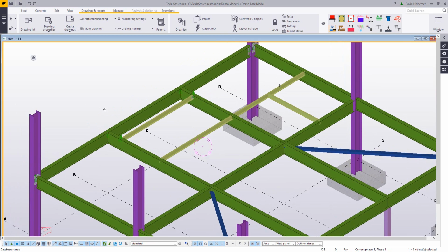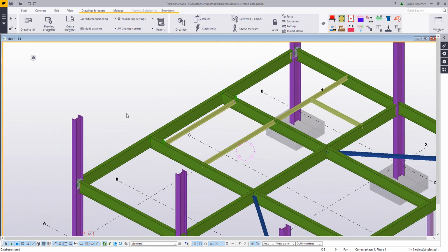And in this video, I want to show you how to use some tools to help you get your decking layouts in a little bit faster. Deck can be created with the beam tool. There's a cross section for different deck profiles that can be loaded in, and then you pick 2 points and you get your deck shape. But being able to lay them out across a broad area a lot quicker is obviously very helpful.